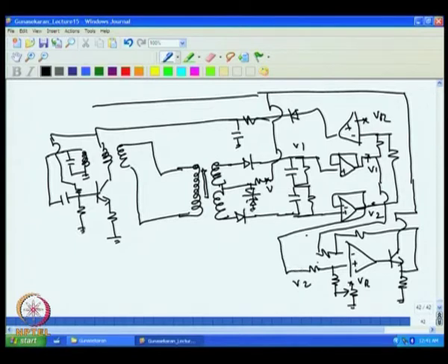So you have V1 here, V2 here, and the difference drives the current through this. So this current I is proportional to displacement eventually, and that can be made 4 to 20 milliampere by suitably adjusting this, and even the span adjustment can be given here using a potentiometer.